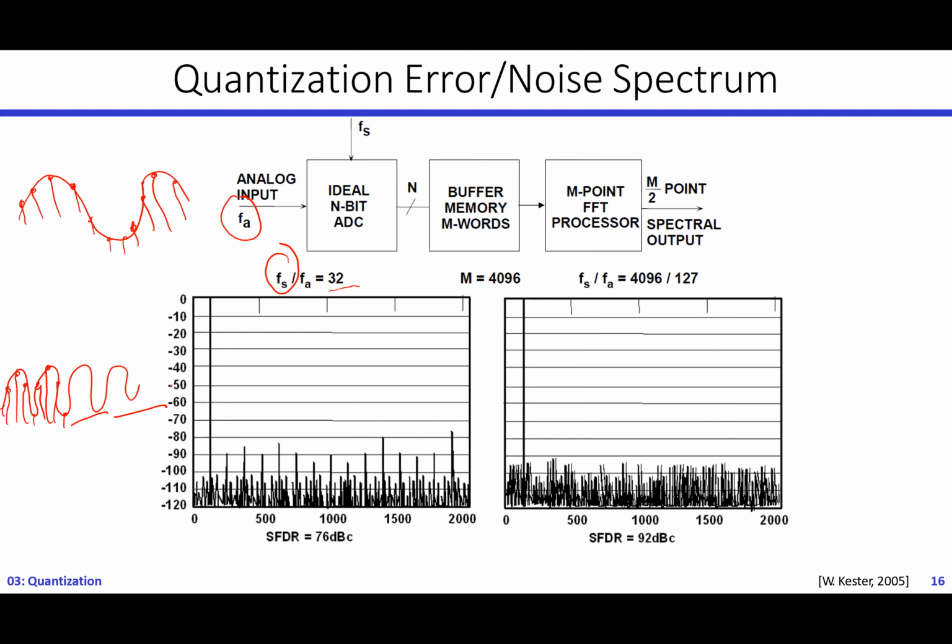The meaning of uniform distribution is that it takes, let's say, values from minus half LSB to half LSB, and it covers all this range equally. If I have the same value of error, let's say minus LSB over three, then this value will occur more often than any other in the range.